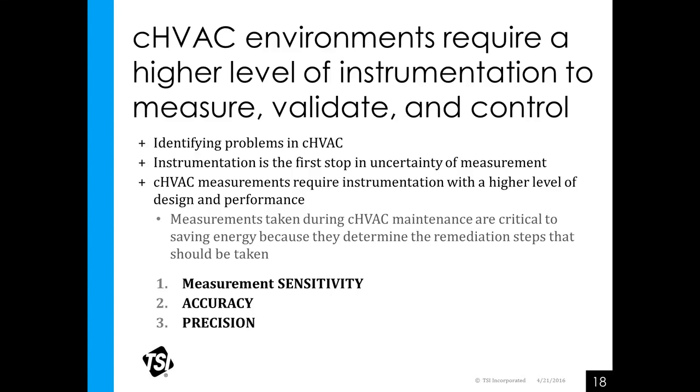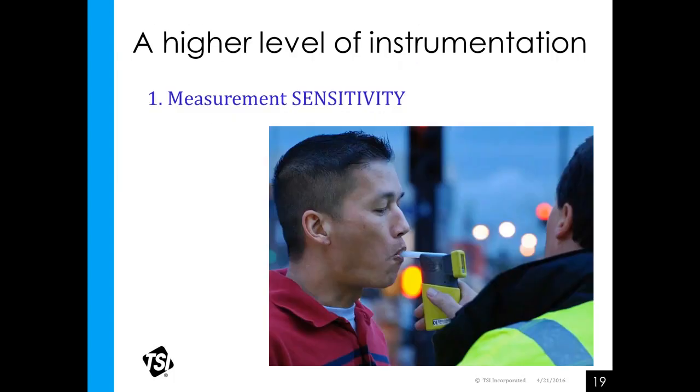I'm sure this guy's thinking about which way on the sensitivity curve do I really want to end up on. If you're looking at your data, you want to evaluate the accuracy and precision of your measurement. It's important to understand, though, your instrument's sensitivity first. A lot of people don't talk about this, but it's there, and it's part of the design criteria, and I think it's important in critical HVAC to understand it.